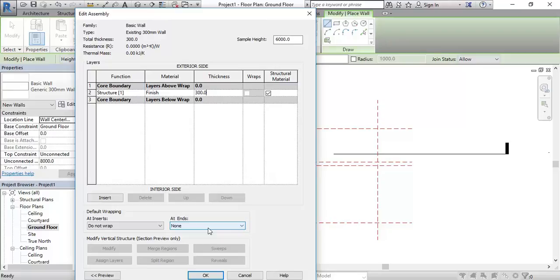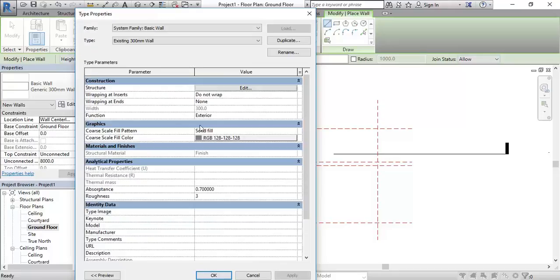So you need to be drawing a wall in the first place. You are drawing a wall, and you've got to have the properties window open, so don't close that. Just type PP on the keyboard, PP, and then leave that open. You can see it on the left there, properties. Okay, so I'm just going to click OK, and I can see there again my width. If you're not sure, you can always double check there, but you can't change it there.